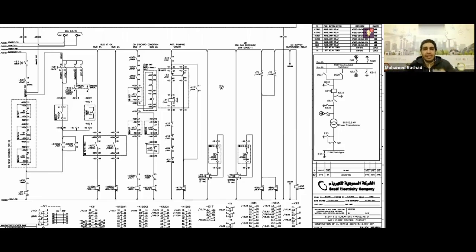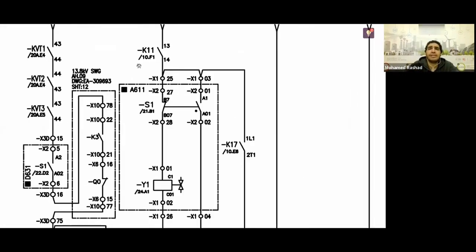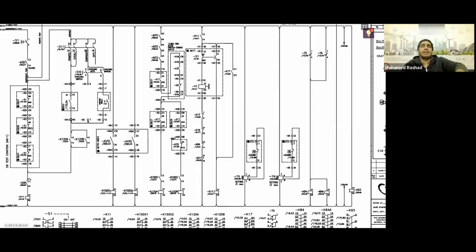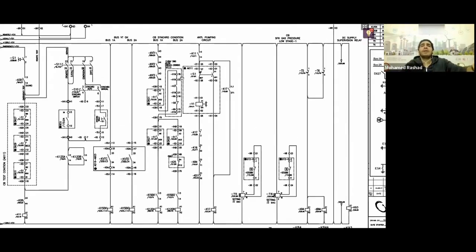Confused? I'll tell you, look, I can answer in 2 ways. The first way is that the breaker factory doesn't know whether you will use it at station 94 or 86, right? Or am I wrong? So you are using 94. And as soon as the breaker opens, there is no closed block, meaning there is nothing to prevent the closing process. The second thing is, let's say the issue occurred in the contact itself, which is K11, the auxiliary contact. If this contact remains closed, regardless of the protection preventing it, you still have it closed. So it will directly go to the closed coil.